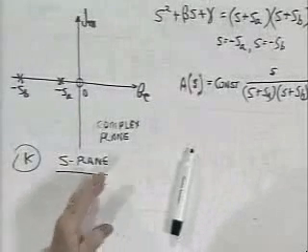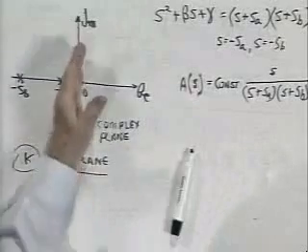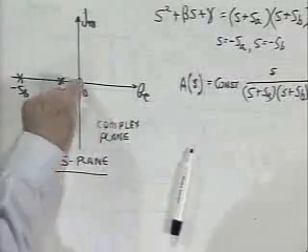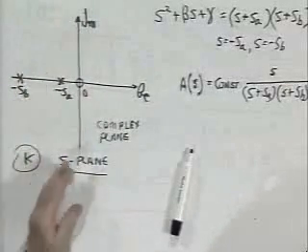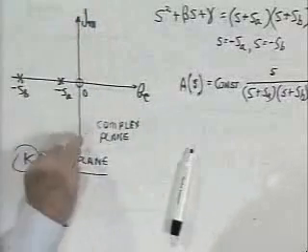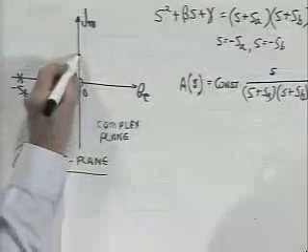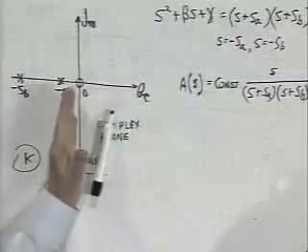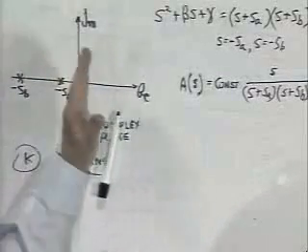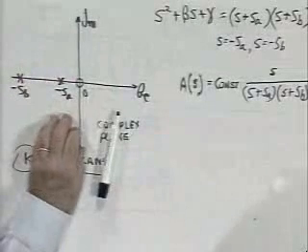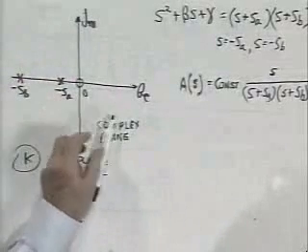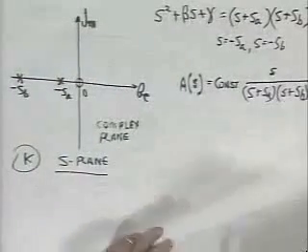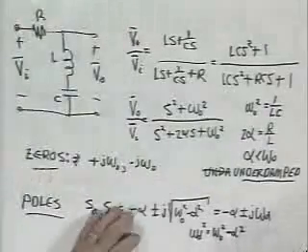And then if you visualize yourself walking along the imaginary axis, if you can imagine a cut through that diagram, nailed down all around the edge, nailed down here, very, very high here and here, if you can imagine a cut walking along that diagram as your frequency moves from omega equals 0 to non-zero omega. The nature of the slice of that complex shape is exactly the magnitude of the transfer function for S equals j omega. It's true on any of these S-plane diagrams.